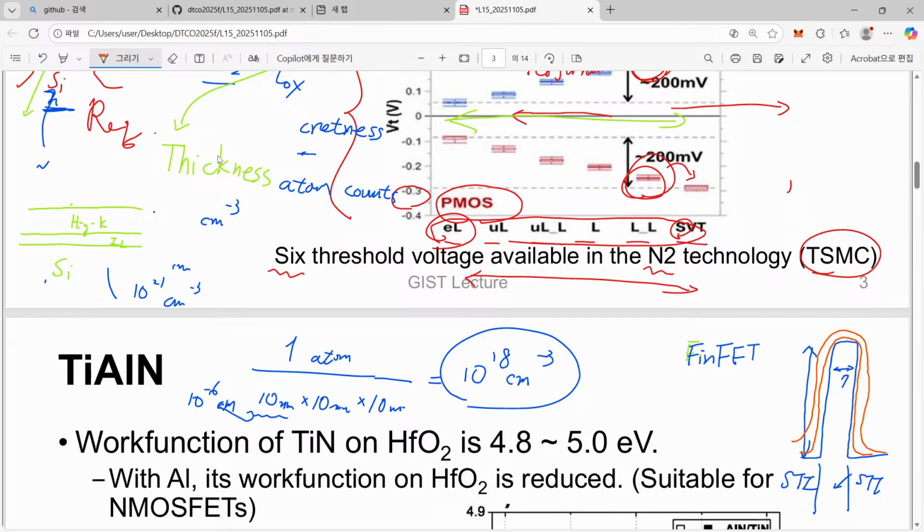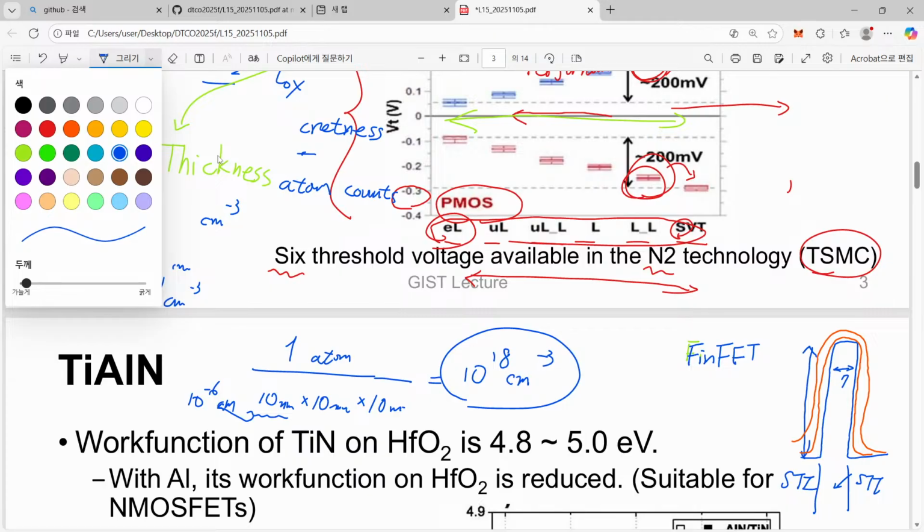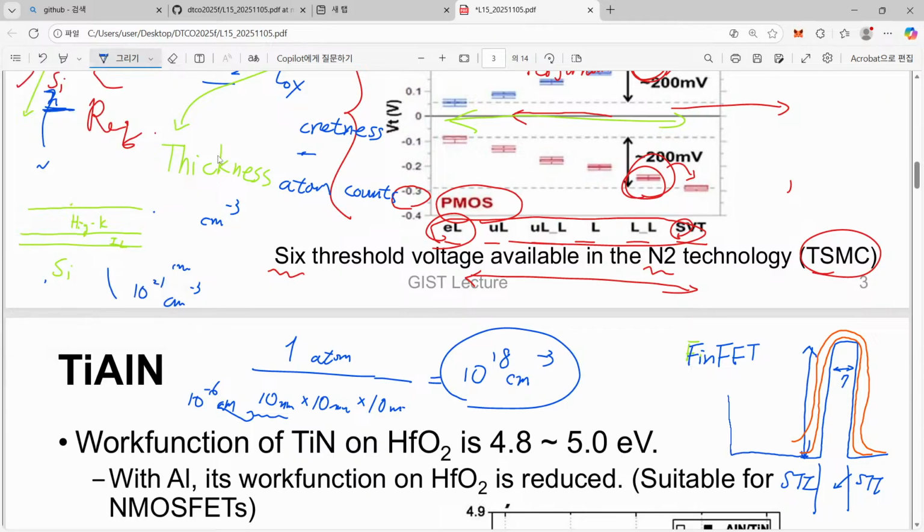After that, if we have to put something on it, then we are actually free to do that, because where can you find your next fin? How much are these fins separated? You can easily understand, yes, there is a next fin somewhere there, and this distance in current implementation is about 20 nanometer, and even when you go to further scaled technology, this distance is not that much scaled.